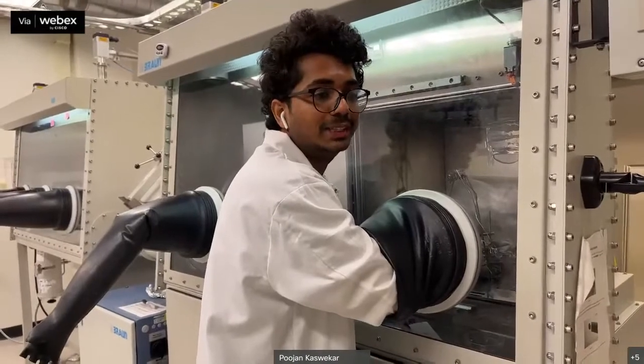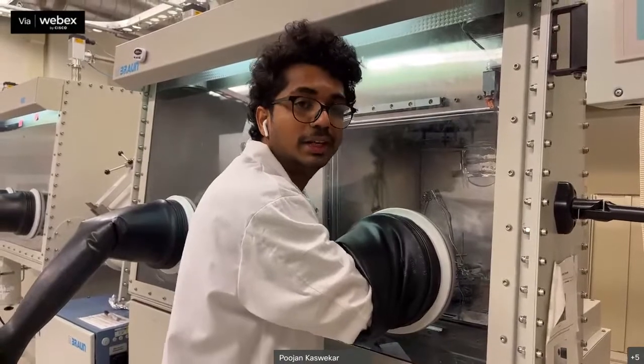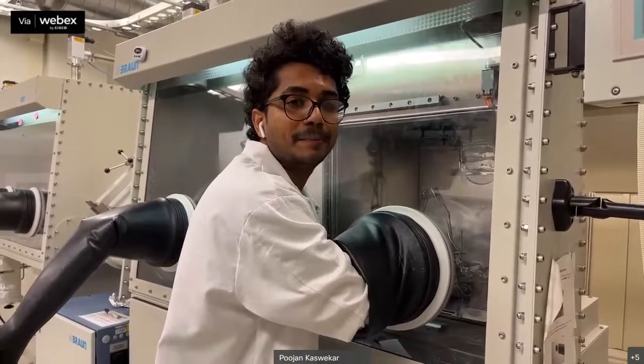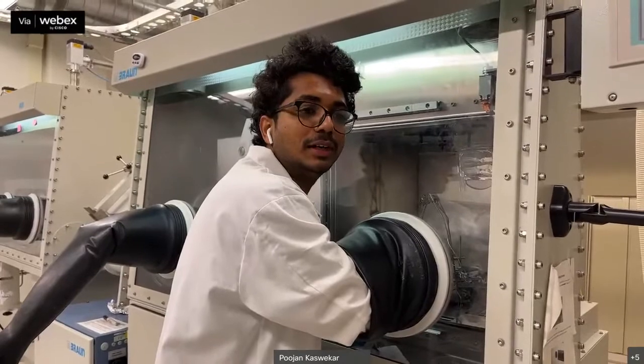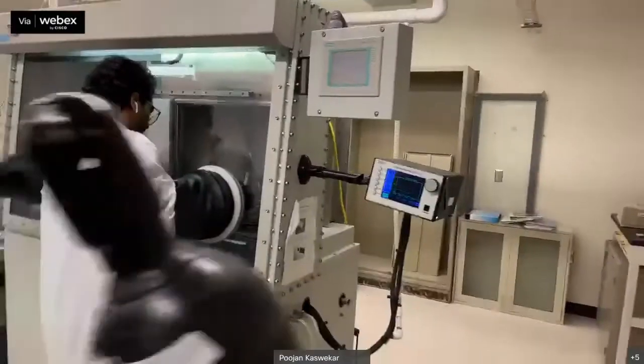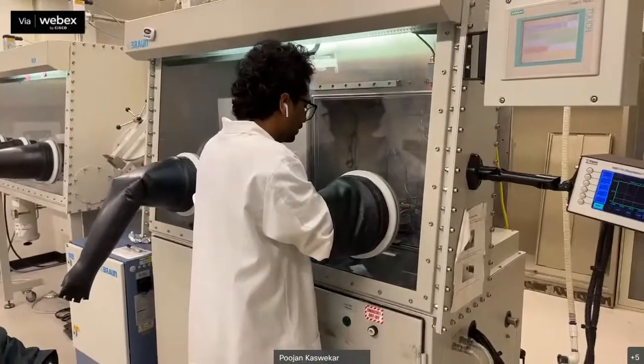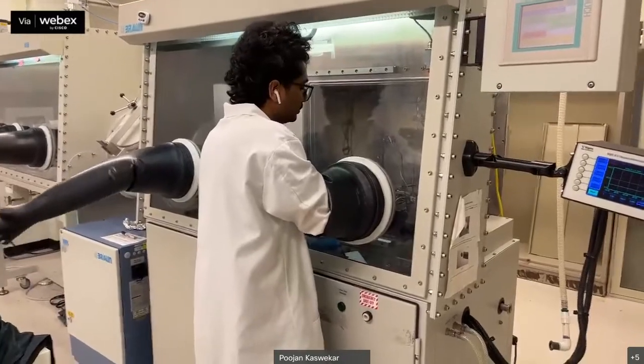A higher deposition rate at the start itself can cause the amorphousness, or oxidation of your silver pellets can do that. It also depends on what material we have used. Sometimes we have to deposit an adhesion layer. For example, if you are depositing on silicon, before gold we have to deposit titanium or some nickel or chrome. Similarly, it depends on which material you are depositing. Here silver adhesion is good, that's why they are using silver.